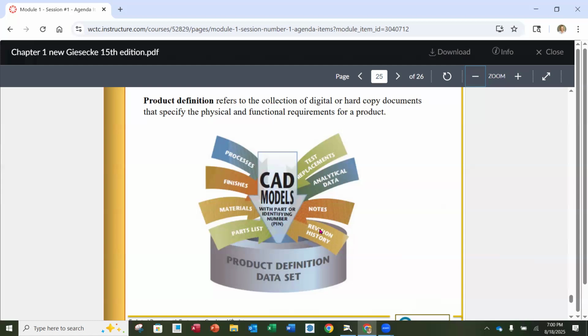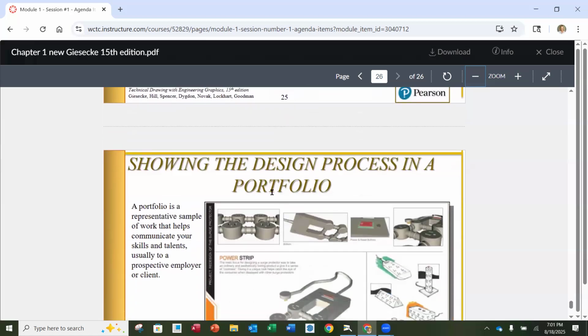Okay. So that's why, like I said, I can't emphasize enough, when you create a drawing, when you create a design, when you release something to production, it's one of the most important jobs and one of the most important documents really in a company. If they're going to be looking at saving money or reducing cost, they start with that drawing and they start looking at, do I need 3 decimal places here or can we get by with 2? Can we open that up? Because the smaller the tolerance, we're going to find out, the longer it takes to make something. It's a smaller target to hit. Can we make that wider? Can we put it on a less capable machine that doesn't cost as much? So that all starts here. So you've got a lot of responsibility, but it's really exciting.